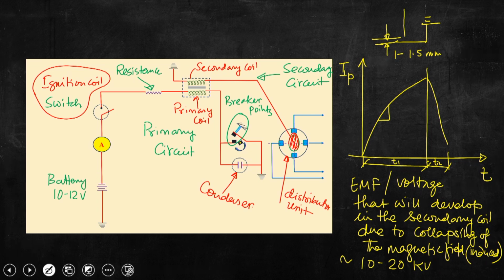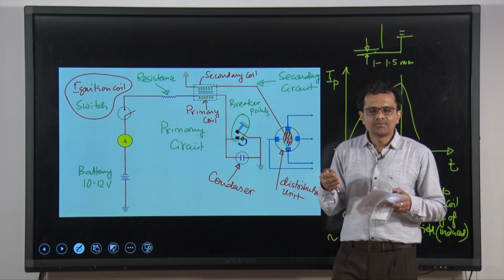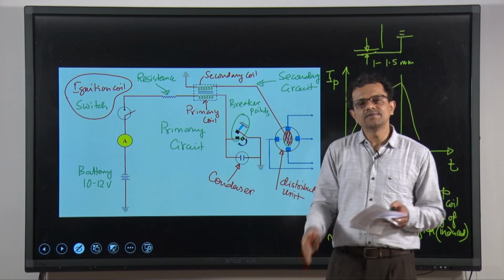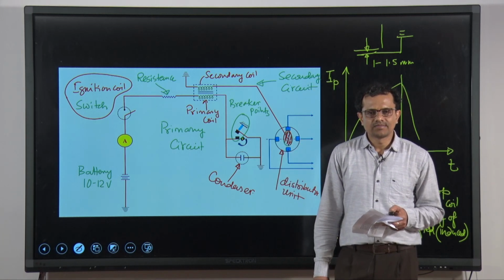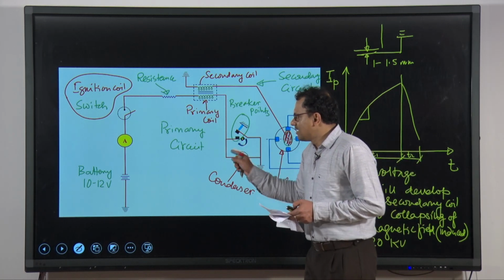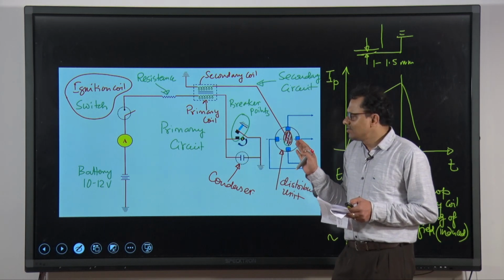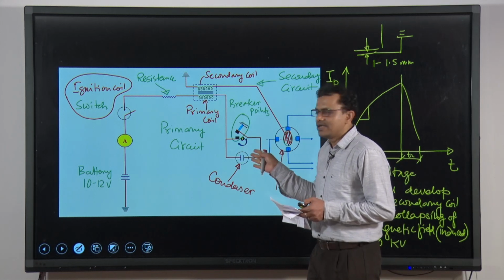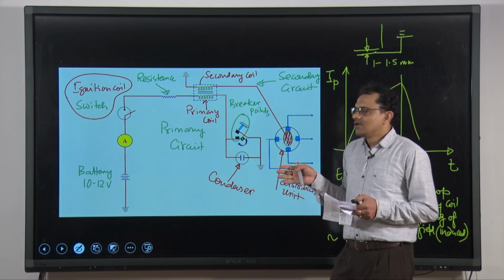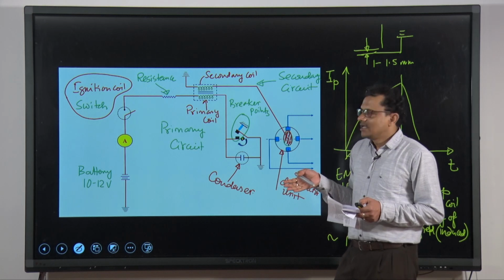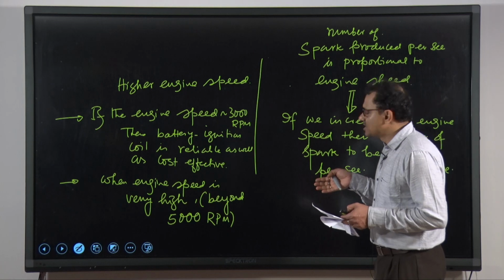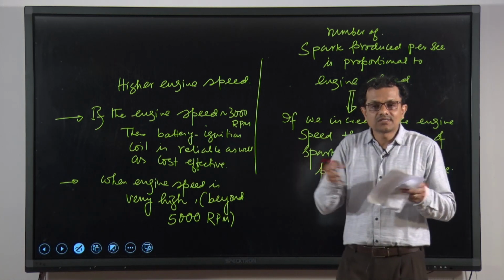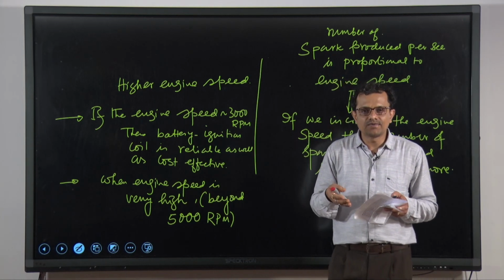So, that is why we need to think about some modification of this ignition coil, and that modification is essentially again with the help of some electronic circuits, electronic gadgets, electronic devices. As we can see, having a look at the schematic depiction, mostly all components are mechanical components, and using these mechanical elements, if we would like to overcome all these challenges, that means if the speed increases, we need a constant energy supply to the spark plug.